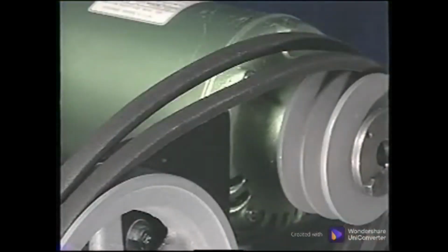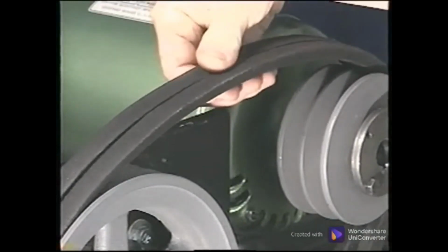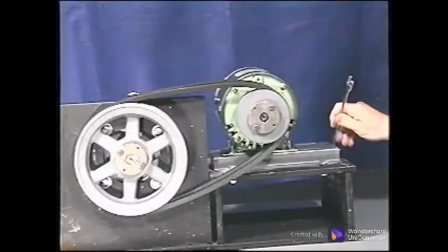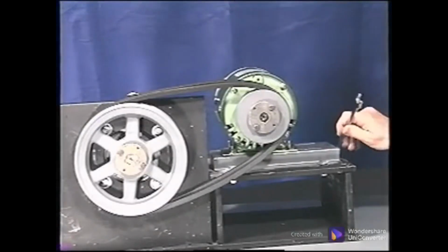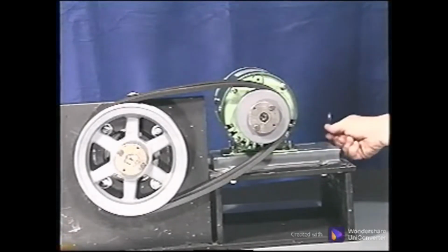On multiple belt drives, adjust the belts so that they are all positioned with the slack side on the same side. As the tension is adjusted, the belts will not be able to slip, but will pull against each other and may damage the belts. The next step is to adjust the motor out until the proper tension is set. Be sure to turn the adjusting bolts the same amount so the motor moves straight back, keeping the sheaves in line.